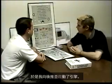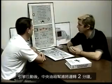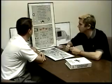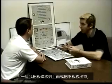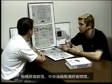So I push back and I start the engines. The center tank pumps are going to run for 2 minutes after engine start, regardless of the slat position. So I taxi out now. As soon as I move the flap handle out of up, the slats are going to come out and the center tank pumps are going to shut off.